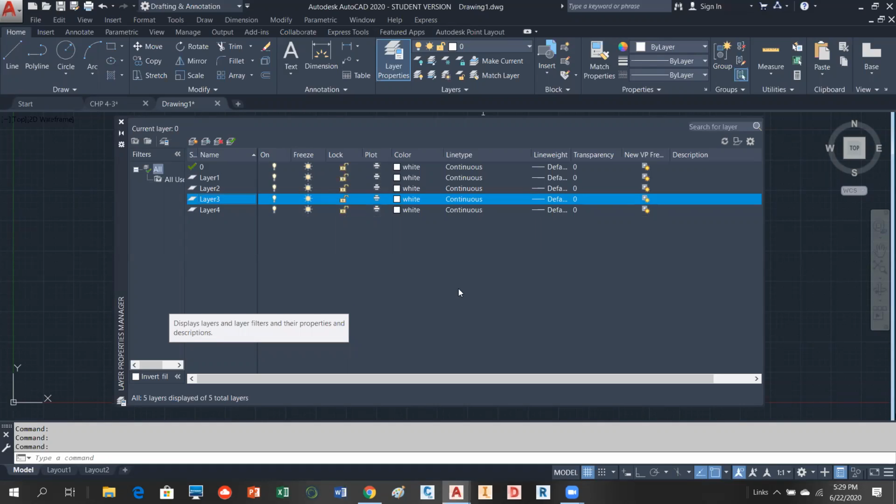Thank you. What that means probably is that you have an object on layer 5, whether you know it or not. You might have drawn a little line object or something else on there. It's not a big deal, but the cool thing is that it will not let you purge layers that have objects associated with them. That's a good thing, if you think about it.